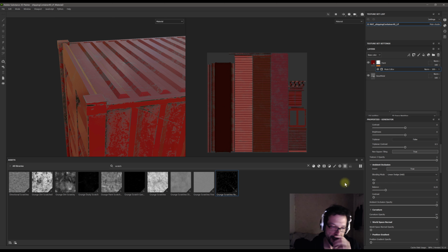inverting this map, because ambient occlusion, as you remember, is darker tones overlaid on top of almost a pure white map. So when I start using it in add mode, it is going to first of all break away all the edge treatment I have provided using curvature, because it is sitting on top of the curvature, right? It is going to get rid of those curvature areas because all of that white coming from the ambient occlusion is situated above the curvature. So add mode adds that white on top of the edges and gets rid of the black. So we don't want that.